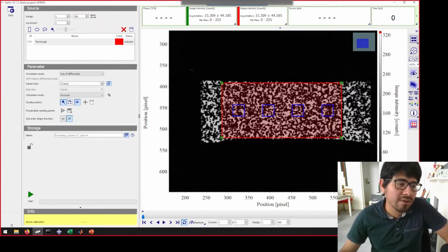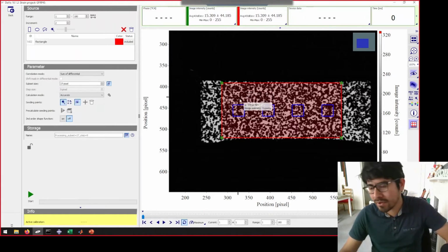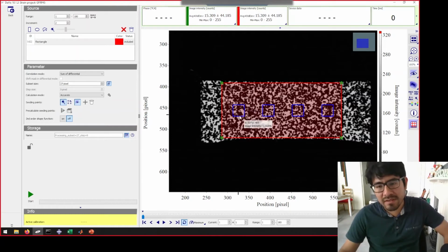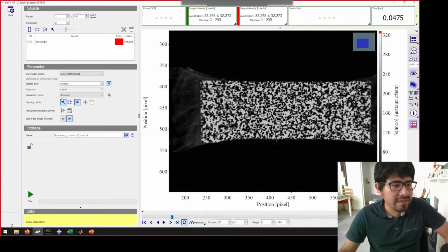But if you select manually, you select a point that doesn't get destroyed during the test. For example, I wouldn't choose a point that later gets cracked. That would not be a good seeding point. But in this case, the program will choose it automatically.